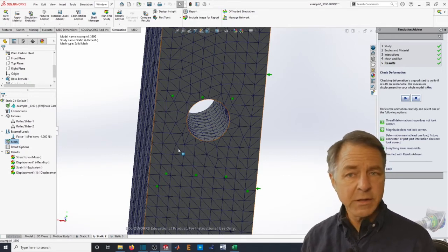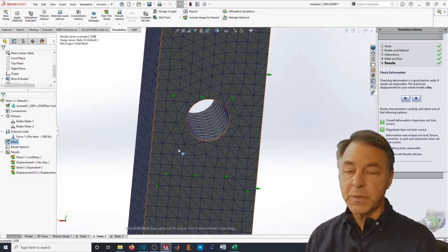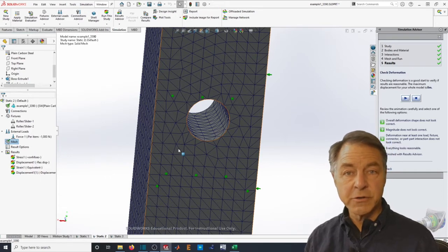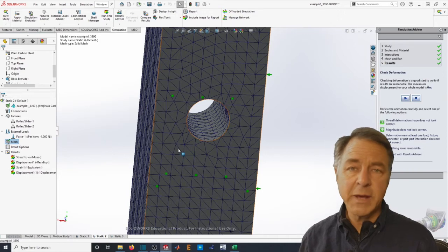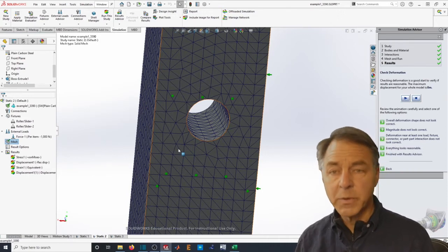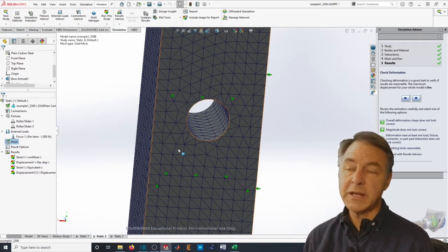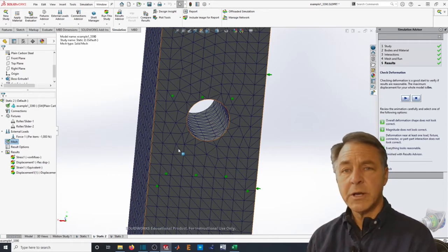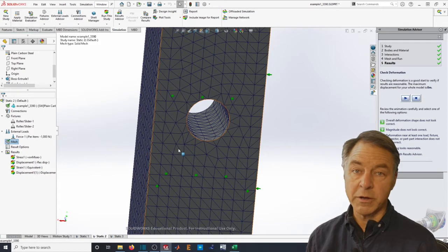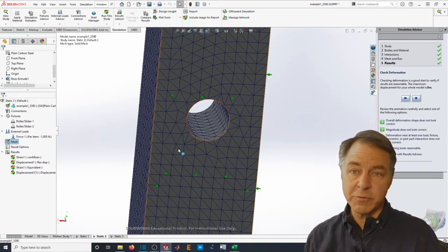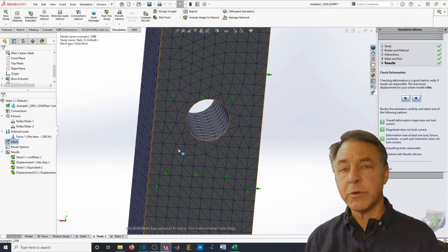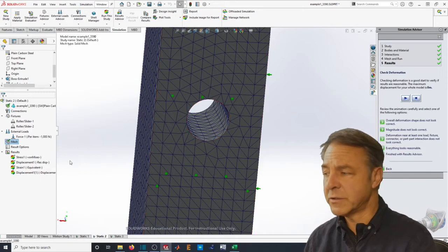But if the fundamentals of the model, the boundary conditions, are not correct with respect to what you're trying to model, it doesn't matter. The answer will still be wrong. Just like if you've got the correct boundary conditions and yet the mesh is too coarse, then the answer will be wrong. All of these things have to be appropriate and correct for each other in the conditions.